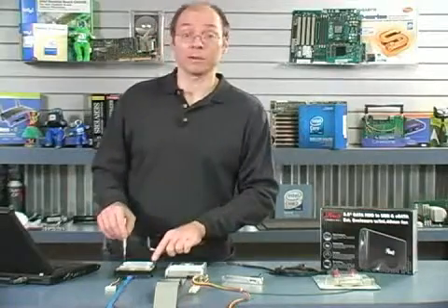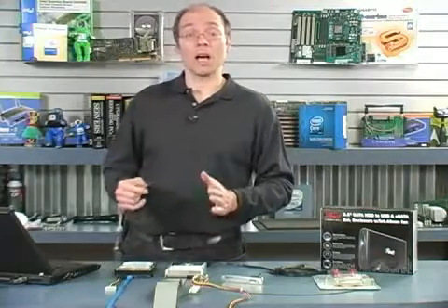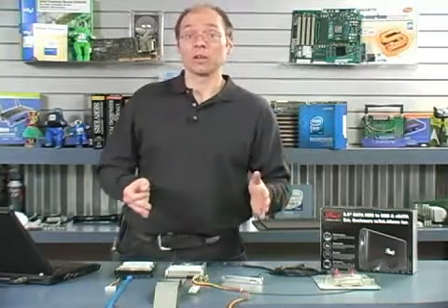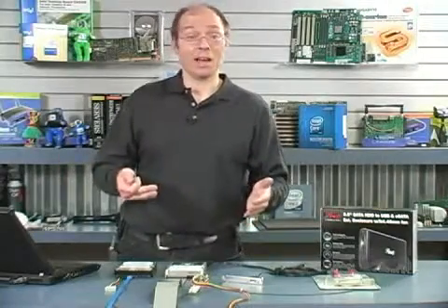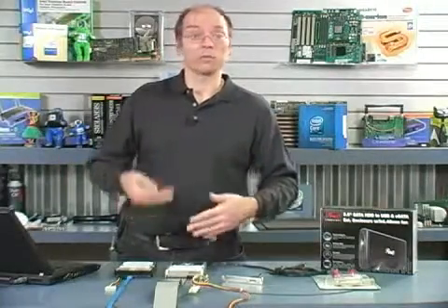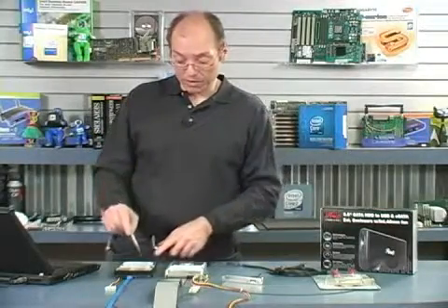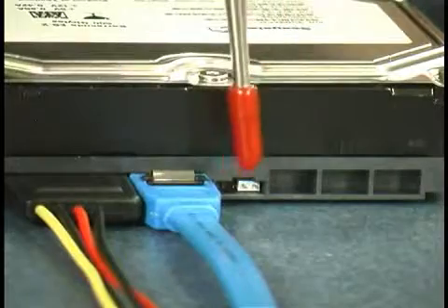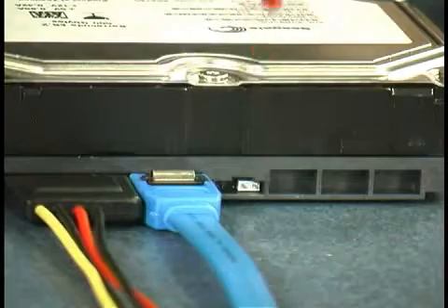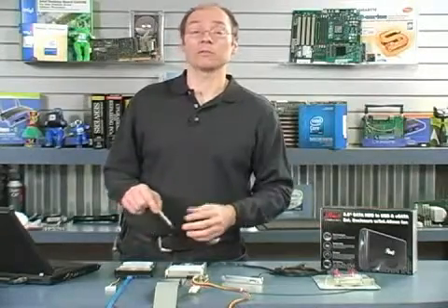This is a 3 gigabit per second drive. However, what was discovered was that sometimes if you had an older motherboard that had a 1.5 gigabit connection and you plugged a 3 gigabit drive into it, they wouldn't talk. The drive would not be seen or it wouldn't work properly. So almost all of the serial ATA 3 gigabit per second drive manufacturers are including a limiting jumper on the drive that will knock the drive down to 1.5 mode. In other words, cut the drive speed in half.